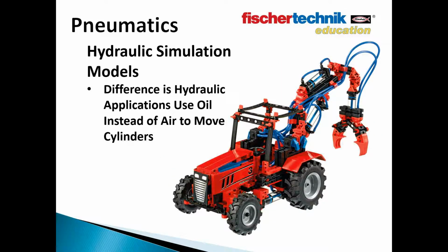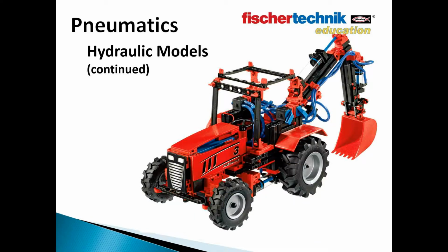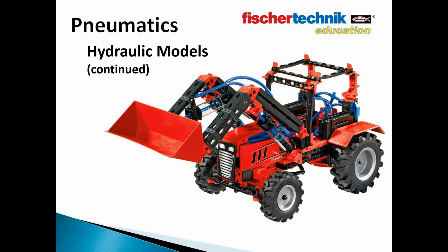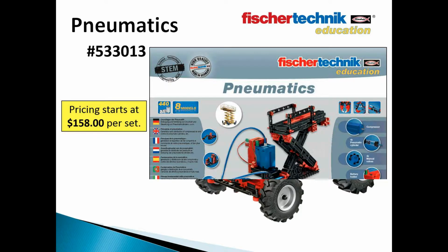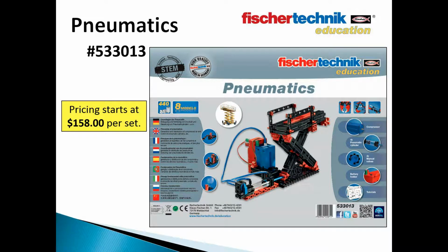The set also includes instructions for building several models simulating those which in real life would use hydraulic instead of pneumatic systems. Students learn that hydraulics differ from pneumatics and that hydraulics use oil instead of air to cause the cylinders to move. In any event, these models provide more engaging opportunities for students to experiment with and understand valves, cylinders, and performing work with air. And that's an overview of what you can do with the pneumatic set.